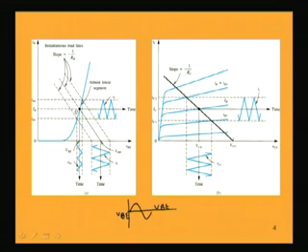Correspondingly, the DC base current is this one. When the signal is increasing, the base current will obviously increase because of more forward biasing. When the input signal falls in the negative half cycle, the base current will also decrease below the DC value.